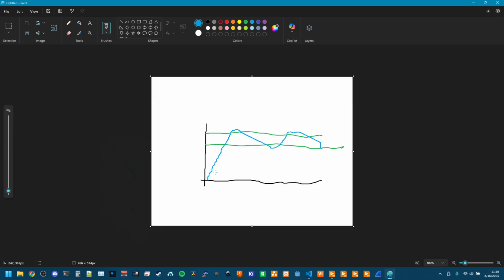Like maybe this is cooling and you've got temperature rising. You need to turn on the cooler when it gets to the high limit. It brings it back down and then turns back off once it's at the low limit. Or maybe you're pressurizing some kind of accumulator or some gas volume. So you need to turn on a pump or open a valve to get it up, and then something is going to consume that gas, and then you need to turn it back on.